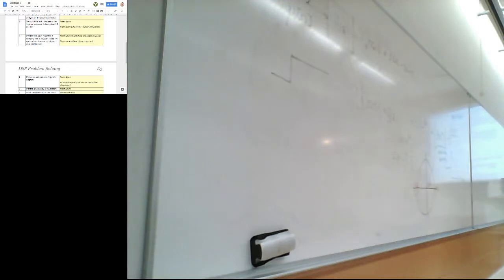Okay, something like that. That will be a low pass filter up to Nyquist frequency. And preferably in dB scale, so attenuation in dB. And then another graph for the phase response, where basically the passband is the interesting part.